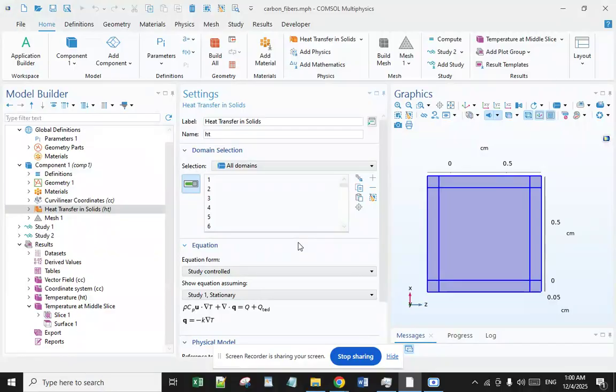0.12 to 0.25 joule per gram Kelvin for the unidirectional carbon NCF, agreeing with the data in the literature. Biaxial carbon woven fabrics exhibited higher Cp values than the unidirectional NCF, in the corresponding range of 0.67 to 0.82 joule divided by gram Kelvin for the NCF 300 biaxial.